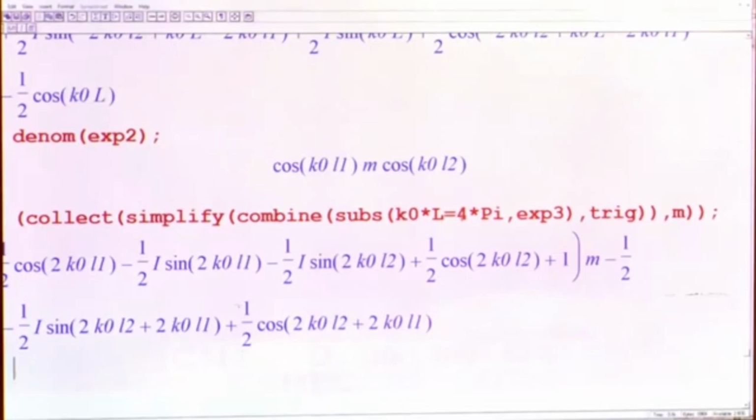If it is L by 2 and L by 4, then it will be very interesting to see that when it is L by 2 here and this is L by 4 here, and k naught has a certain frequency, it will so happen that the numerator and the denominator will behave in such a manner that the argument of the logarithm in the transmission loss will never be equal to 1. That is to say, it will be a large quantity, and that is why you get a very sharp peak there, transmission loss theoretically tending to infinity.